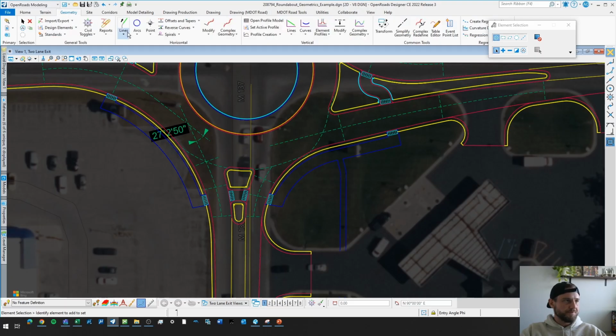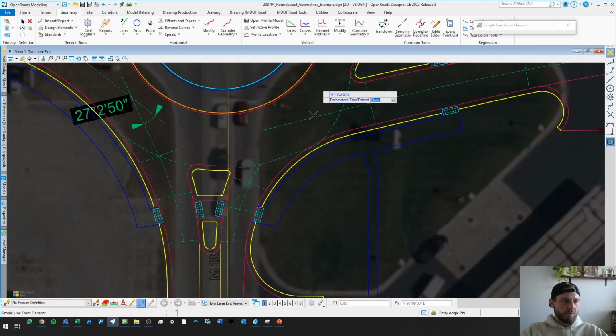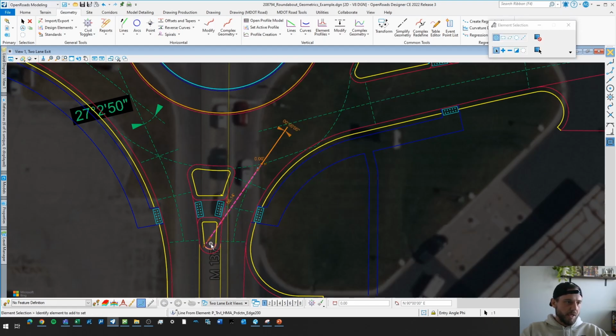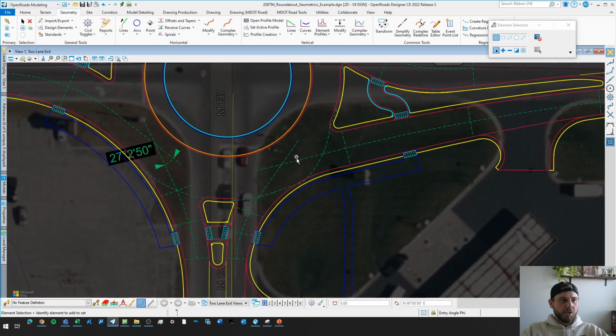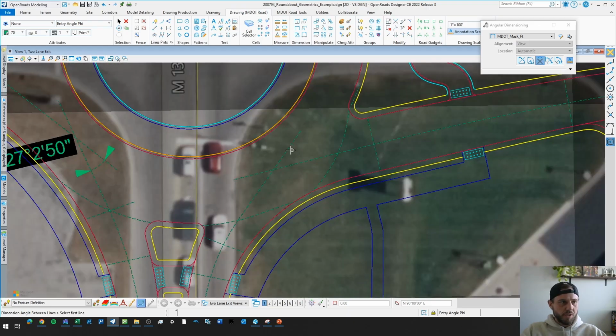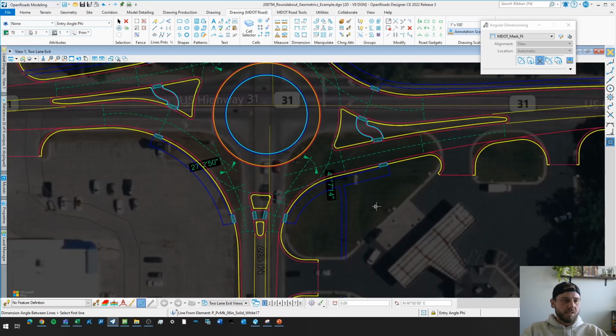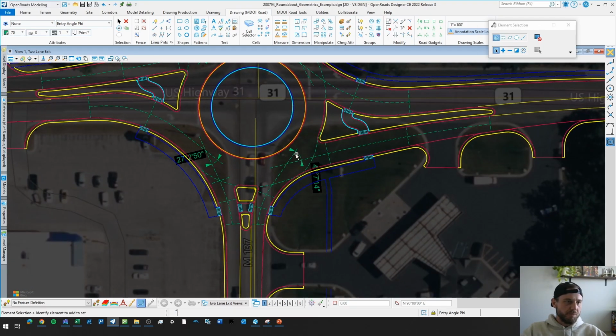And then you want a tangent from this point, so I'll do a line from element. Now that that's squared away, and right from that point, I'm just going to shoot. And sometimes it goes backwards, depending on the curve direction, but not a big deal. You can just take this and reverse it. So I'll do one of those, and then from there you want the angle in between that these cross. So I'll just take this one, and I'll take an angle between these two lines. That's giving me 41 degrees, 7 minutes, and 14 seconds. From there, you can convert that angle.